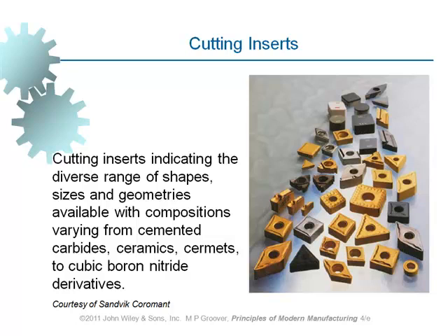However, high-speed steels cannot be used for cutting really hard materials. If this is the case, then we've got to make use of inserts. We've got different types of inserts. Some of them are shown here. We've got, for example, carbide inserts, ceramic inserts, cermets, etc. Each of those inserts provides a different set of properties in terms of, for example, hardness, toughness, and geometrical shape. And depending on the type of the material being cut, we've got to choose the right type of insert.